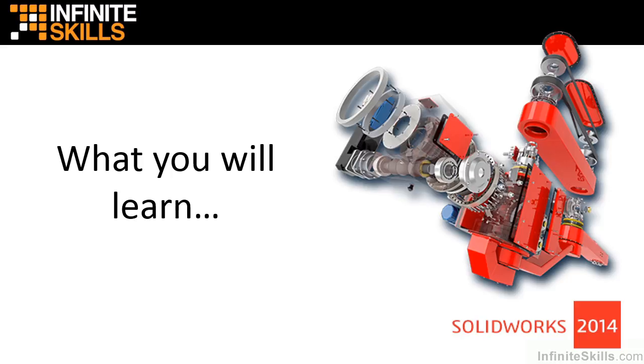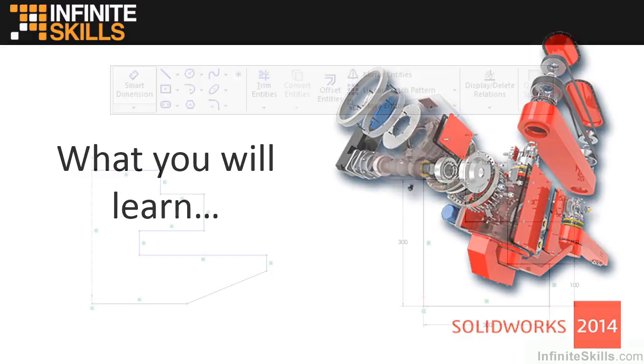For example, let's say you want the hole at the top of a soda can to stay on the top surface, regardless of the height or size of the can. SolidWorks allows the designer to specify that the hole is a feature on that top surface, and will then maintain the design intent no matter the size or height of the can. Let's begin talking about what we are going to cover in these lessons.